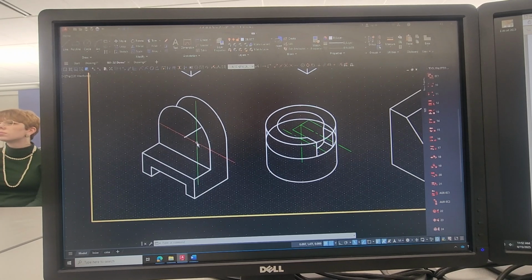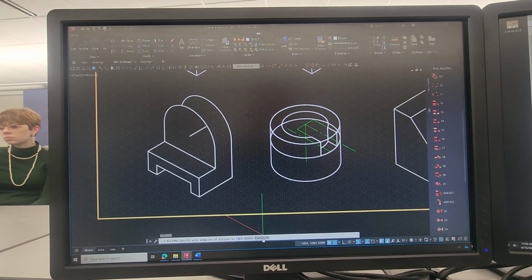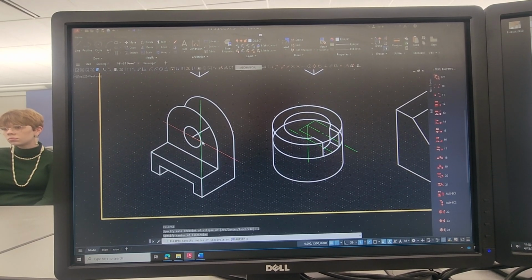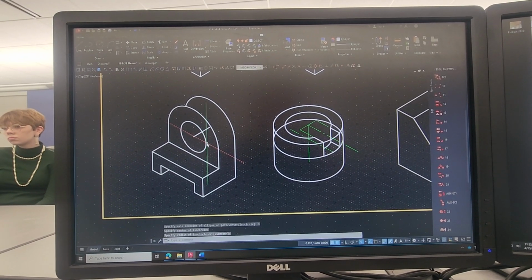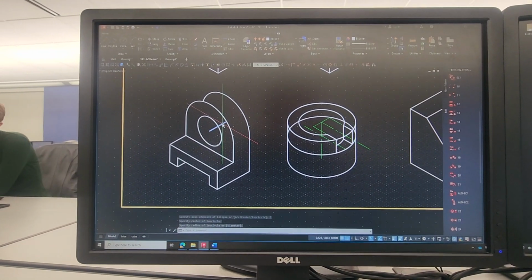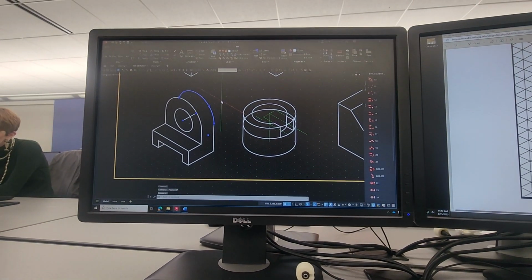When I go to do that ellipse command, ISO circle, I can choose where I'm going to start it. It's at that same point, but now I have to walk along there. There's one half, where there's two, and there's a half. See what I mean by that? Now, you'll also notice I left this line on there. That line is also the dead center of that ISO circle, correct? We all agree with that.